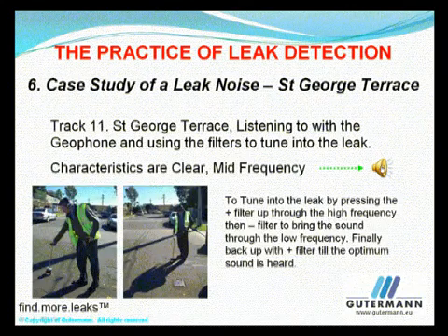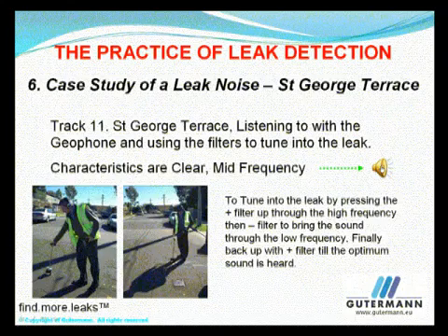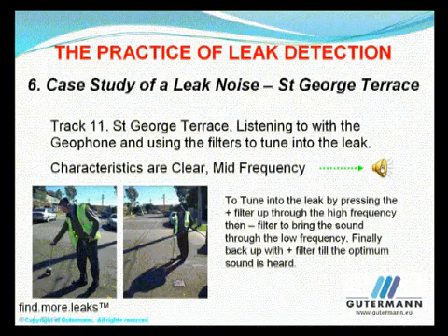This soundtrack provides an example of the process of tuning in the leak noise with the filters. After 10 seconds the filter is turned on. Then the plus button is pressed, going up the frequency scale. Once the top of the scale is reached, the minus button is pressed until the bottom of the scale is reached. And then the plus button is pressed to tune into the sound of the leak.